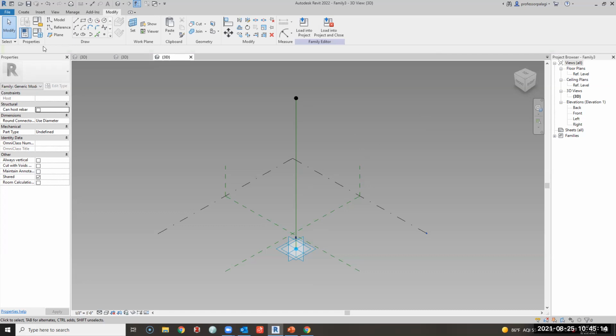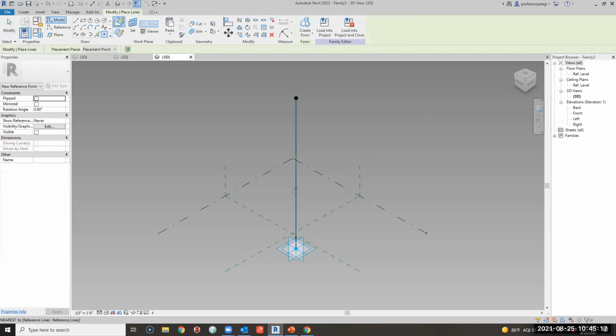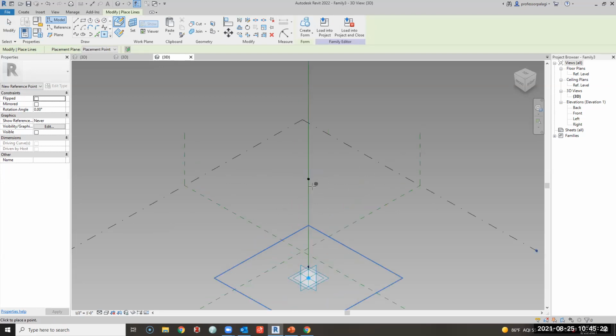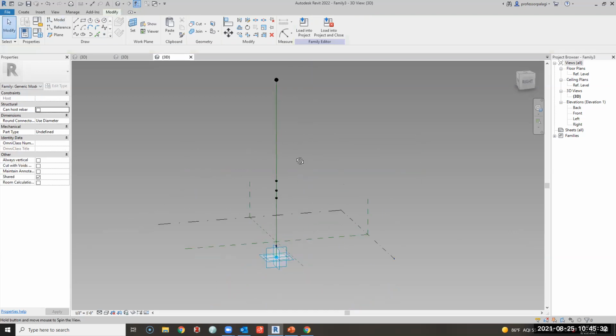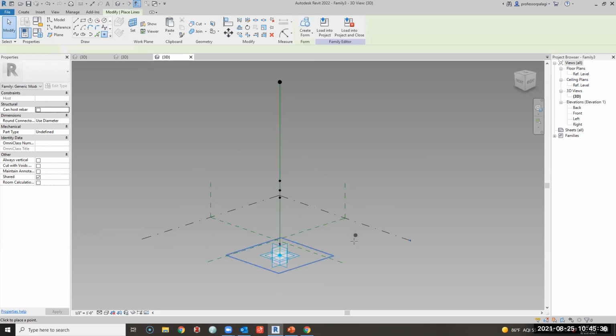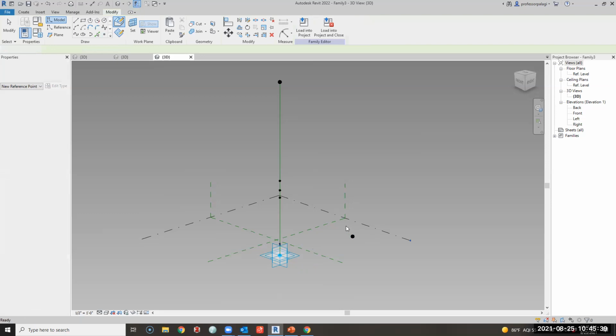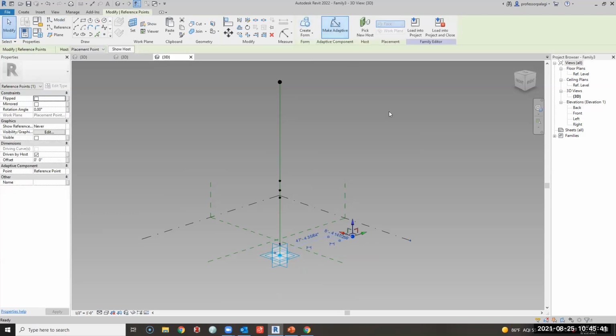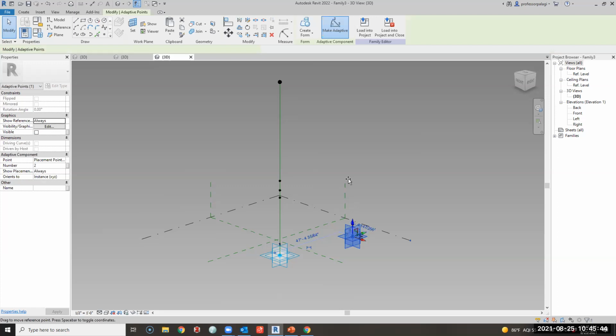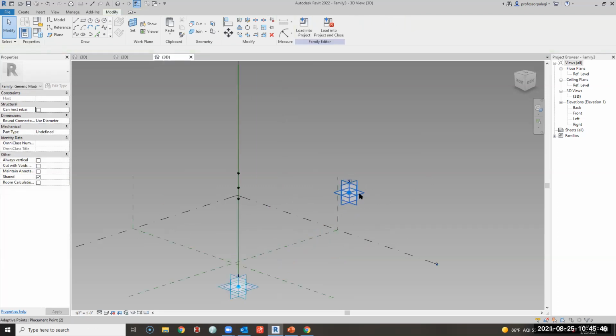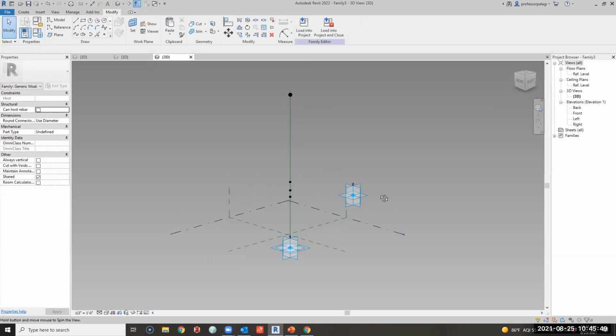Okay. Now, this is another thing we do all the time. I'm just going to put a point on here anywhere. Actually, I know I need 3 points, right? I know I want 3 points, 1, 2, and 3. I'm also going to, just for my own sanity, put another point right here, but all of a sudden I'm going to grab that one and say, I need to make that adaptive also. I'm raising it up a bit. So I know it's a little higher.